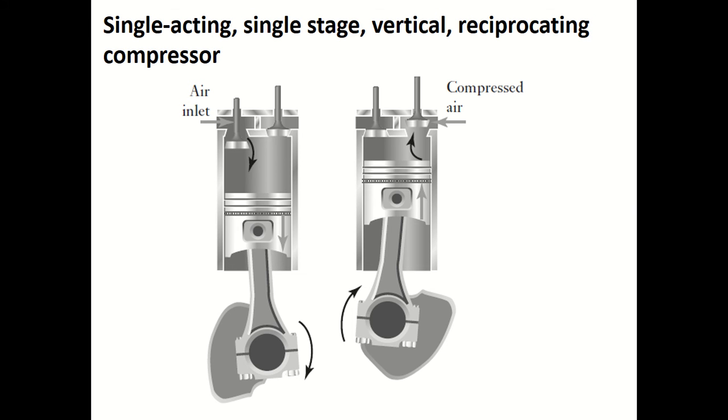Initially there is the air intake stroke: the piston comes down and causes air to be sucked into the chamber through the inlet valve, which is a spring loaded valve.